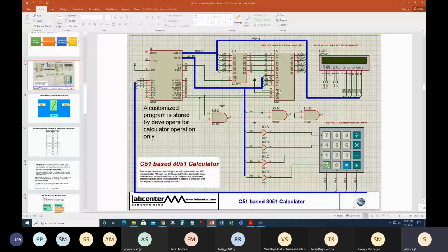Okay, in addition, CS and CE bar are two additional controls, given just to make sure that you have two-way control. Multiple microcontrollers may be present, so in that case also you can have some control, or through some logic combination you have to enable the entire chip. One is active low, the other is active high, and the remaining part is just based on the design, how you are selecting the LCD module.